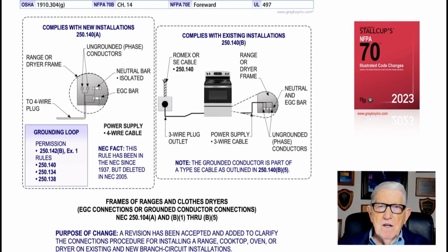So they're saying you have an 800 amp main, so you have to take the 1 AWG and pull it in each raceway. You cannot take the 1/0 and divide it by 3 and pull that circular mill rating in each raceway, then combine it and add it up. And that's what your 3 bullets or 2 bullets are relating to the user of the NEC, and that's what this revision is pointing out to the user of the NEC.